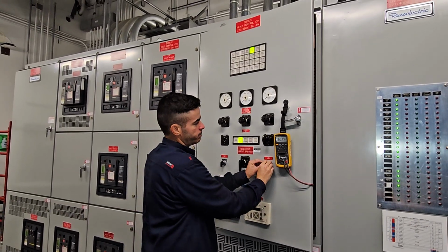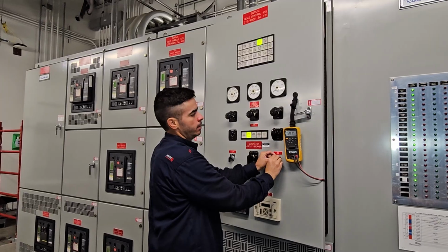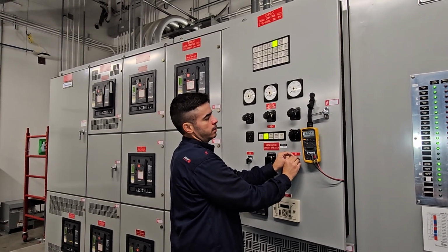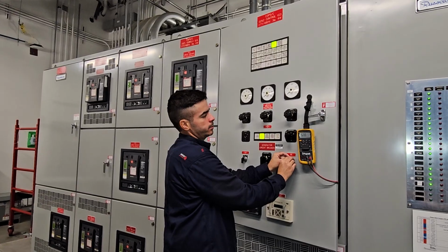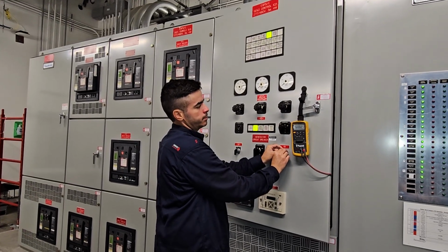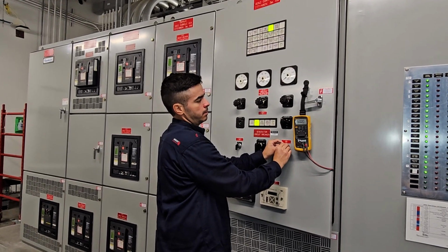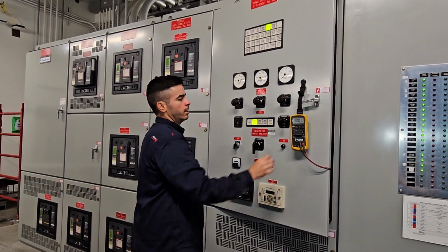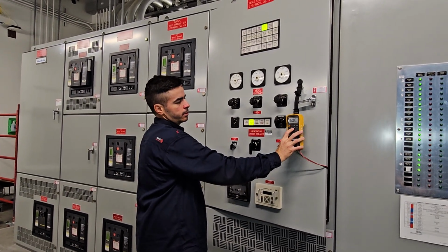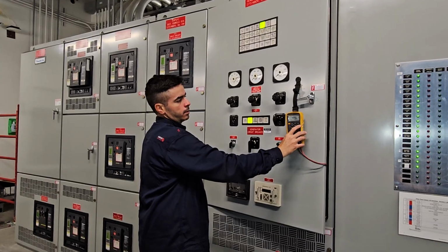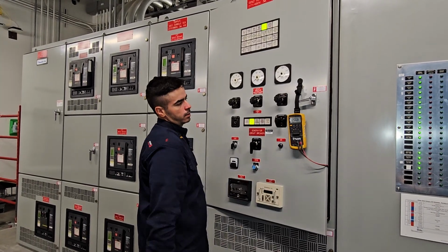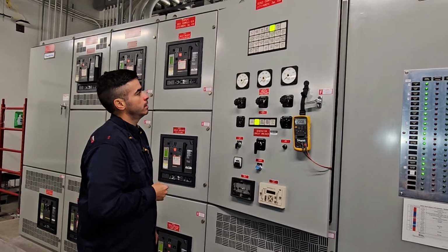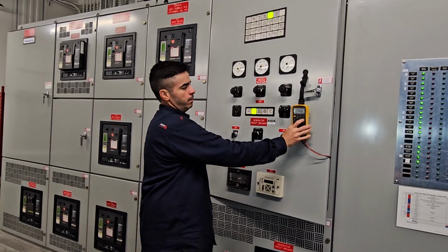But this is why it's important after the PM, we check this. So I'm gonna set it up almost to 60.01; 60.02 is acceptable. Okay, and then the voltage should be almost the same as the other one, 200.7 was the other one. So it looks pretty good now.